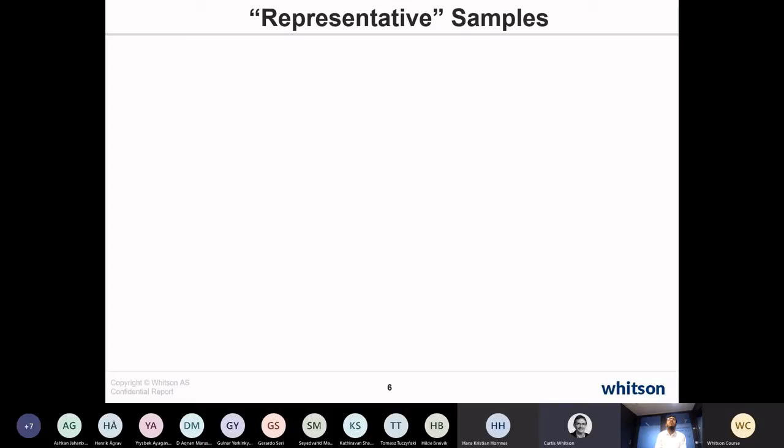The effect of water solubility on gas oil vapor-liquid equilibrium, that I'm quite familiar with. There's an effect, but for the most part, it can be ignored in terms of the effect on bubble point, dew point, and hydrocarbon liquid dropout, things like that. 99+% of the time, it won't matter. Taking the water out of the sample, taking the H2O out of the mixture when you do the PVT measurements and modeling, is not a problem.